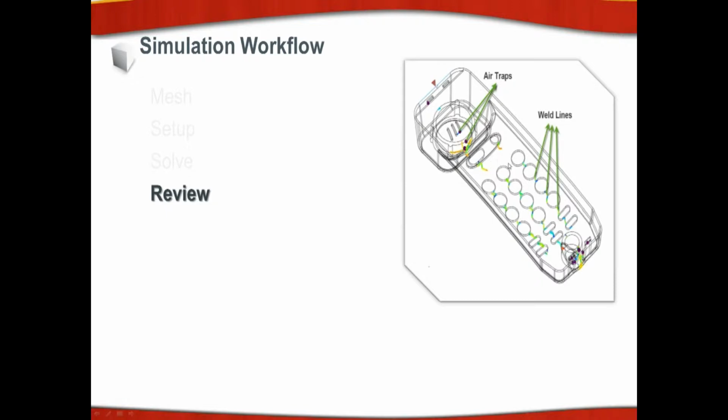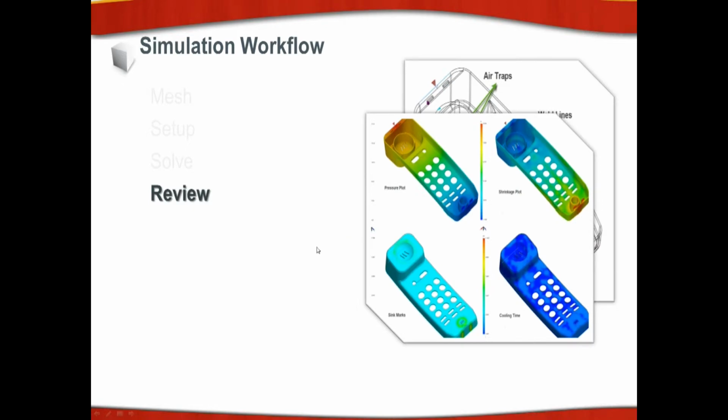And then, of course, as the plastic flows around buttons and things like that, where the plastic comes together and starts to cool, it can create weld lines. So you want to make sure that these weld lines are on the backs of the surfaces so they're not on the show surface of the part, so that customers don't see that. So you try to eliminate those or move them, add a little bit more plastic or remove plastic to make sure that it looks right.